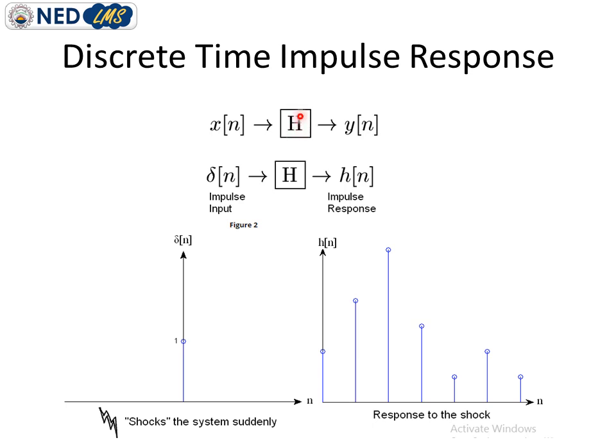So h is basically representing the impulse response of this system, and what this equation is justifying is that if we know the input and if we know the impulse response, then we can determine the output of the system, which is the very basic definition of convolution too.